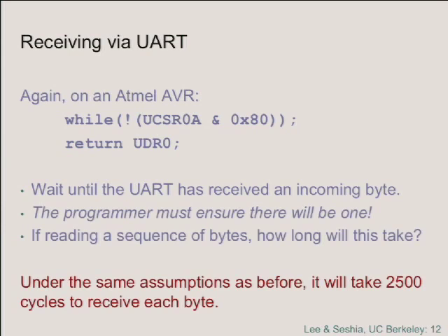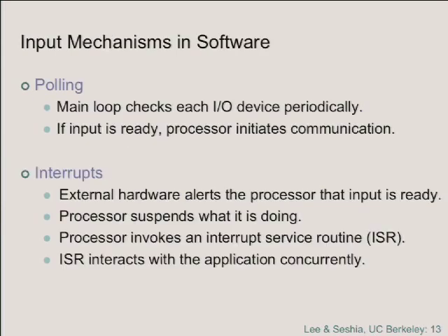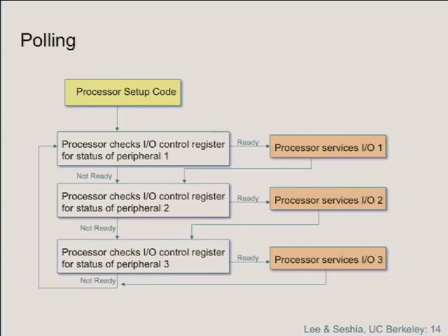And in fact, in a lot of safety critical systems, they're simply disallowed. Everything is done by polling. Okay, if you have a safety critical system, you may be forced to do that, because it can get really hard to be guaranteed of being able to control what's going on when you've got interrupts happening. But interrupts are very commonly used, and they can be used very effectively and very reliably, but you really have to understand what's going on.